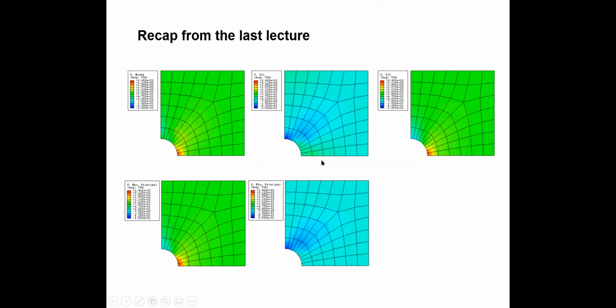You can see the different analyses: this is the von Mises analysis, this is shear stress and other things. I already discussed these, so I'm not going through everything in detail. We can find the Kt value using this kind of graph in the exam. According to geometry and loading condition, you need to select the proper graph, then you can find the Kt value according to the ratio of d/h and d/b, like that.